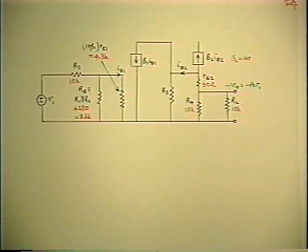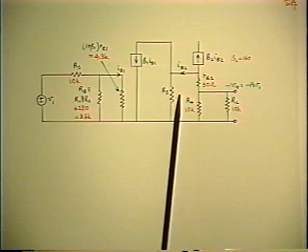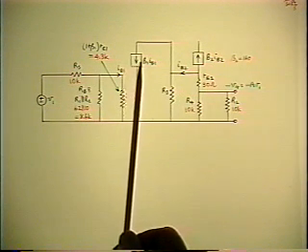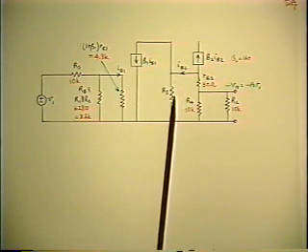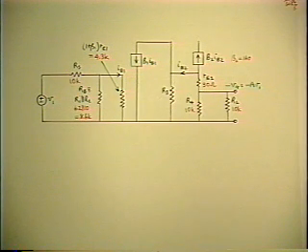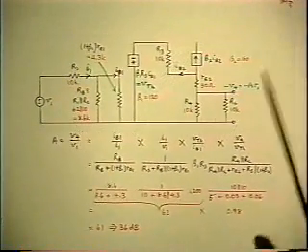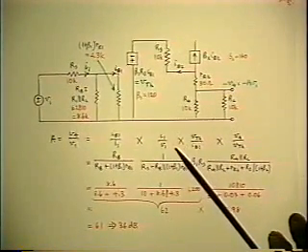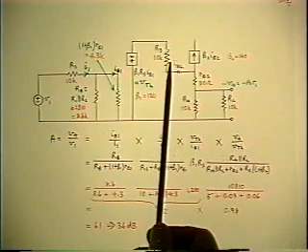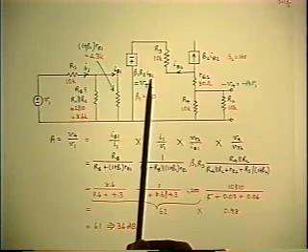That's the first modification. The second one is I now have two loops in the middle because I have what amounts to a Norton equivalent. I have a current generator in parallel with R3. I can get rid of one of the loops by using Thevenin's theorem. Again, one of the basic techniques: reduce the number of nodes and loops. So I'll replace the Norton with the Thevenin, which gives this. So now the R3 is in series with the corresponding voltage generator.